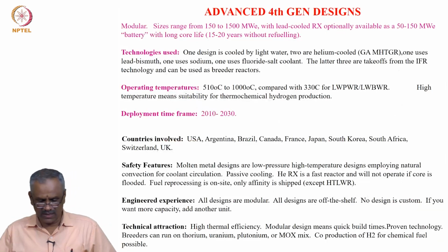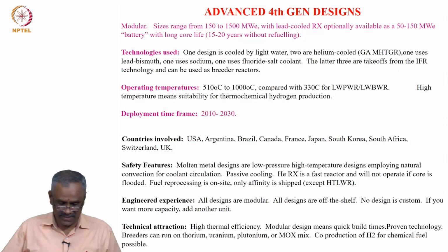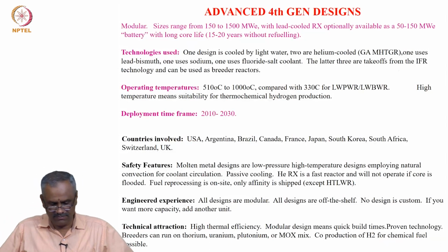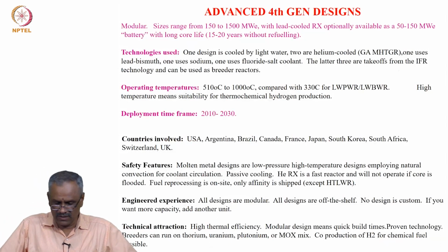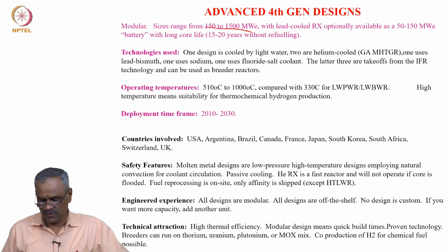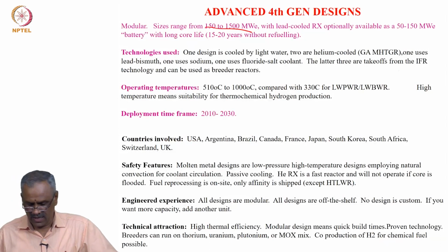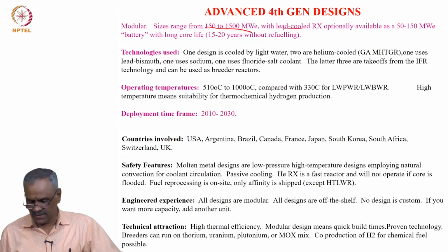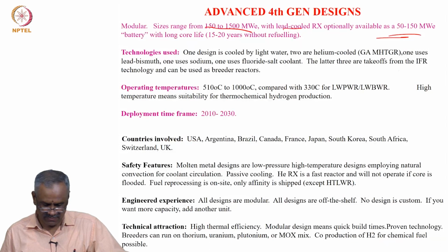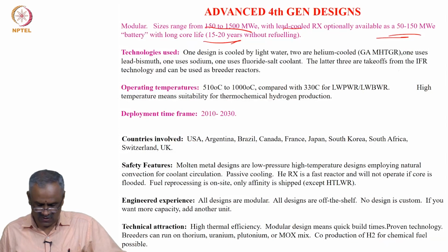Then if you look at the advanced 4th generation designs, they are modular, with sizes ranging from 150 to 1500 megawatt electric, and they are lead cooled reactors. Optionally, a 50 to 150 megawatt battery is also connected, and the life is 15 to 20 years without refueling.